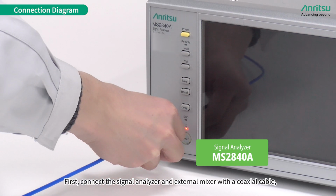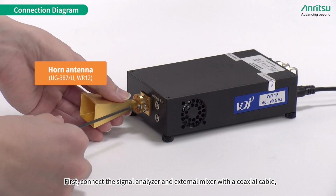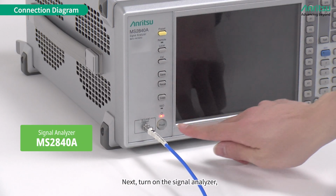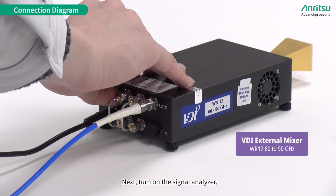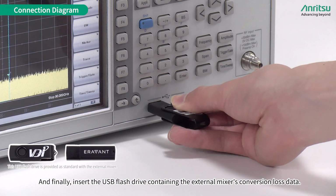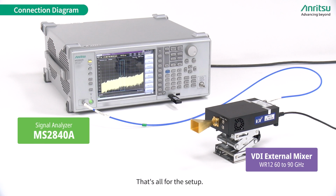First, connect the signal analyzer and external mixer with a coaxial cable. Next, turn on the signal analyzer. And finally, insert the USB flash drive containing the external mixer's conversion loss data. That's all for the setup.